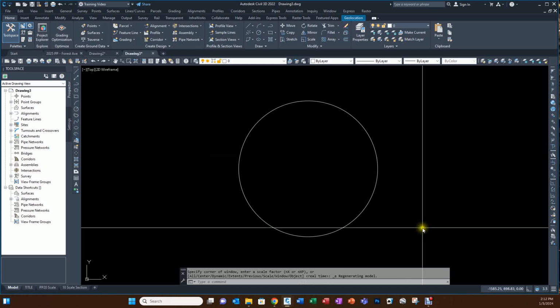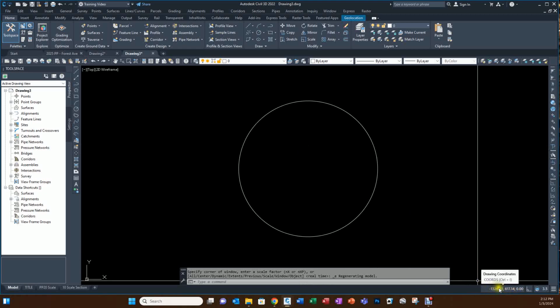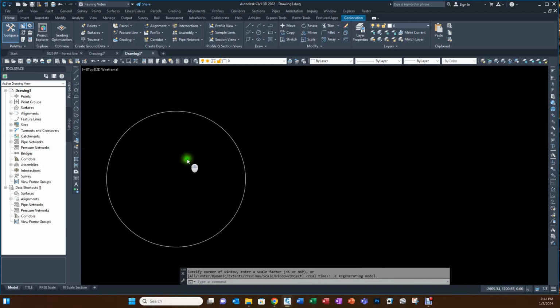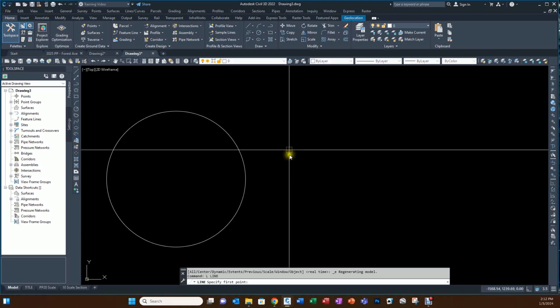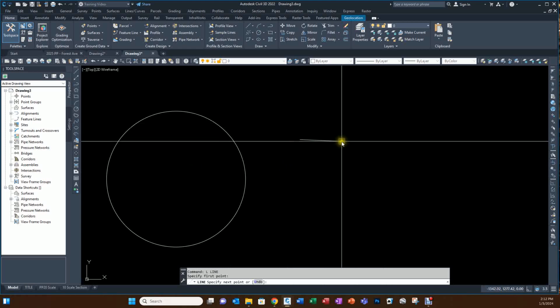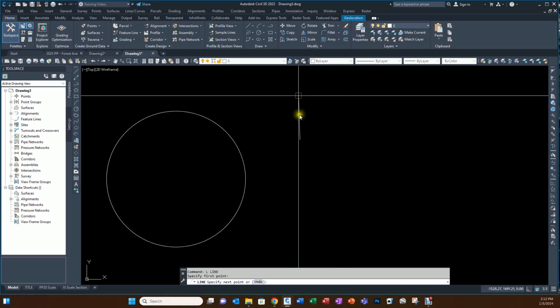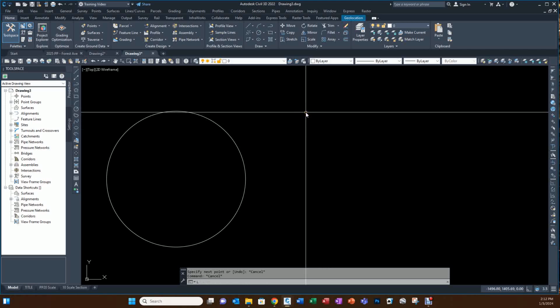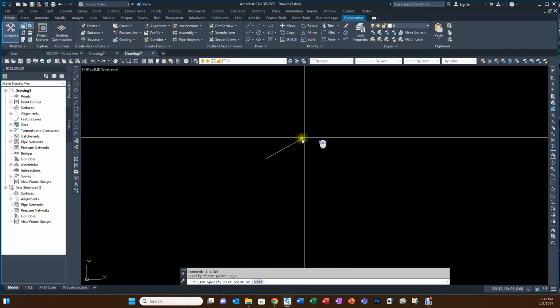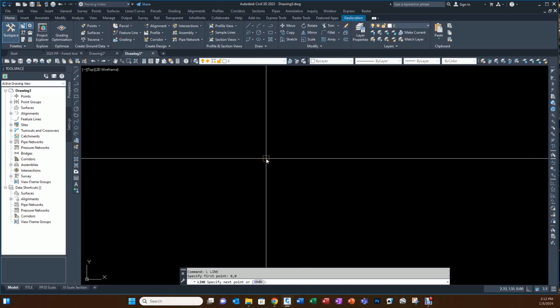So a couple of quicker little commands there. And the coordinate system down here is where you're at. If you want to draw things in relative locations, I can start a line command, and it's always X and Y when you're doing this. So if I start a command and I say 0,0, this is the 0,0 of the entire coordinate system right here.